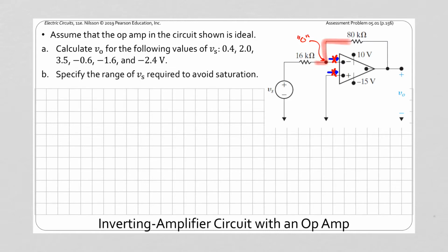And so we're going to have a current flowing in from our signal, and a current flowing in from our output, and we know that those two are flowing in the way that we've defined them. There's nothing flowing out, and so our KCL equation is thus. Then I can rewrite both of those currents in terms of the voltage differences and the resistances for each one.